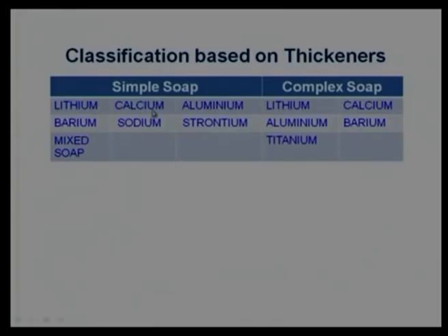One of the most commonly used simple soap greases is calcium based soap grease. It is most commonly used and many times it is called all purpose grease because it has temperature sustainability up to 65 degrees centigrade, and the operating temperature is not going beyond 65 degrees centigrade. Calcium grease will work very nicely, generally used for low speed applications.